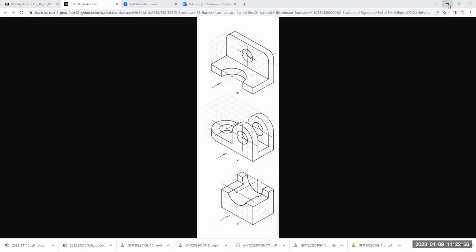Now, if your object snaps are on, you can grab points and pull them down. So I'm grabbing that upper endpoint, pulling it down. If you're careful with that and your mouse is quiet, not active, right? If it's too active, you'll lose it every time. If you had too much coffee, in my case, it just doesn't work. But I can pull it down and get all these helpful horizontals and verticals lined up. And I can be confident that that's right on the money. You want to be confident with that or don't do it. So there's that.